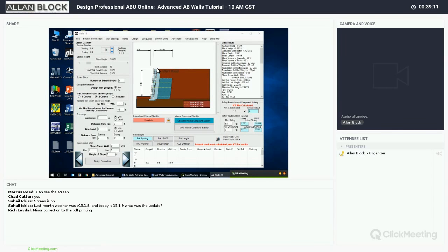And so this is going to be treated like a complex composite structure. And so you can see now instead of just one sliding and overturning value, I've got lower and upper values. So the lower structure sliding and overturning, upper structure sliding and overturning. Obviously not much there at all, no concerns. So we could treat this as a gravity wall.